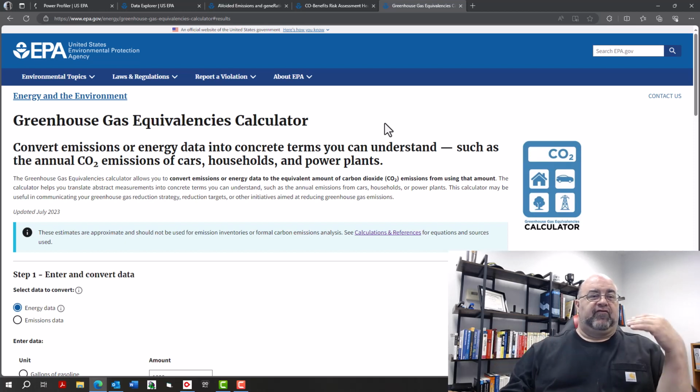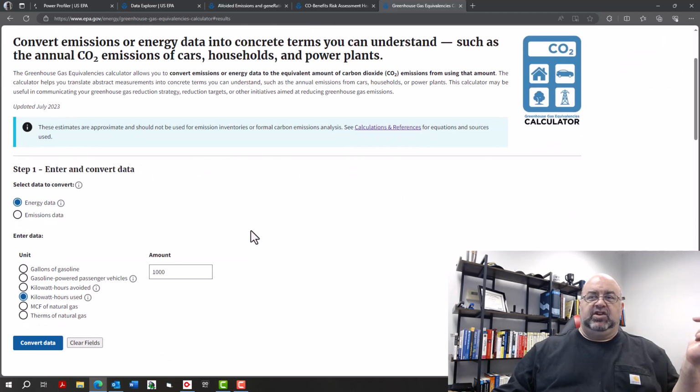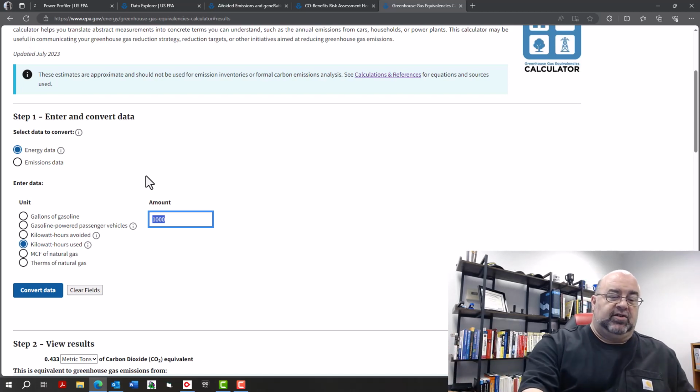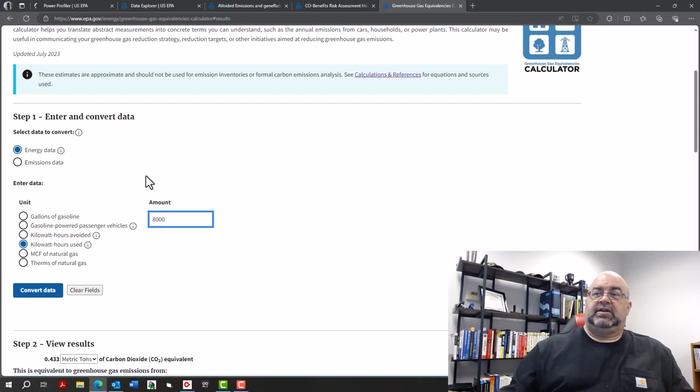So going from a misalignment, which may be costing me, say, let's do an example, using a national average, say it's a kilowatt loss, and I'm running 8,000 hours. That's 8,000 kilowatt hours, so 8 megawatt hours. Convert the data.